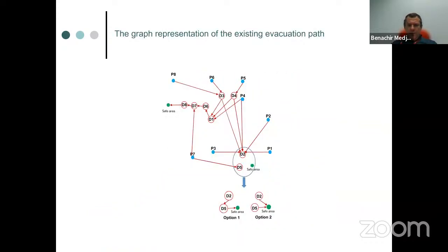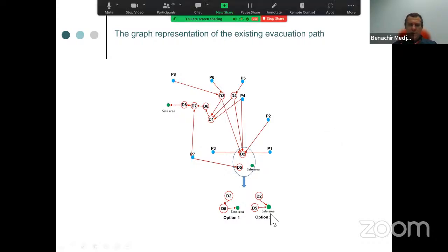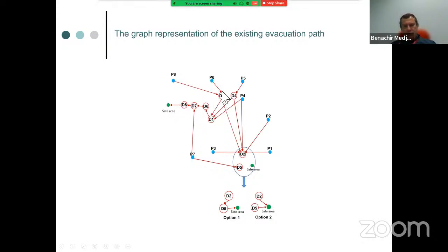Then we developed a constraint-based circulation model. The doors are indicated by the letter D and correspond to the nodes, and the arcs correspond to the circulation, the distances. The doors are characterized by a location XY within the space of the building, a coordinate point which allows them to be in any position on the wall.